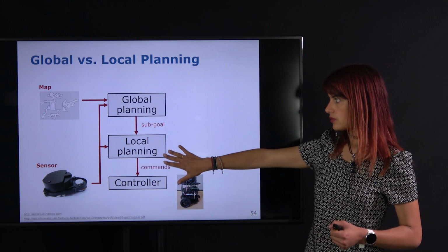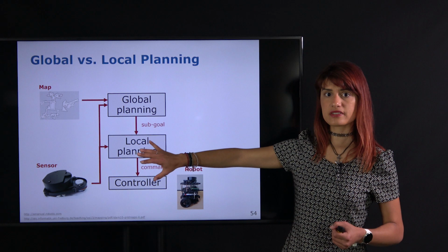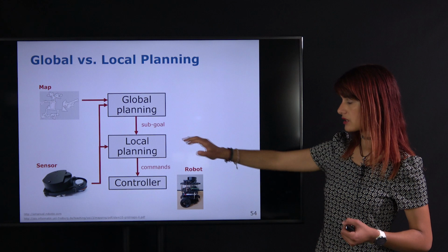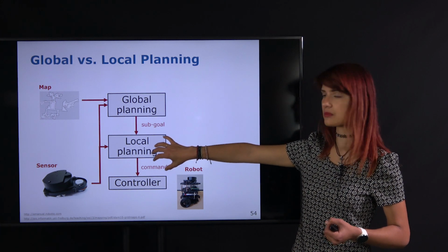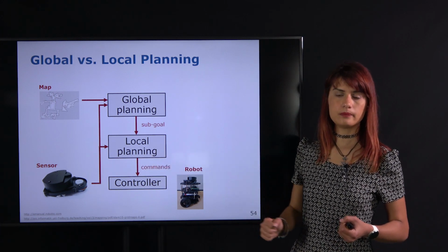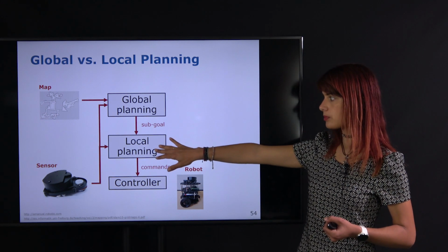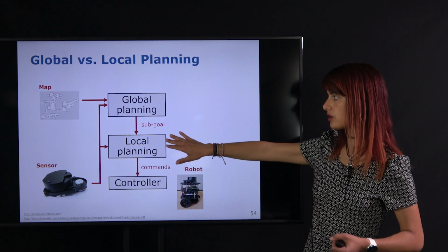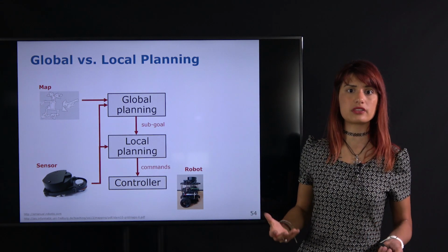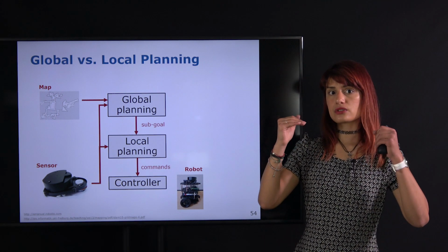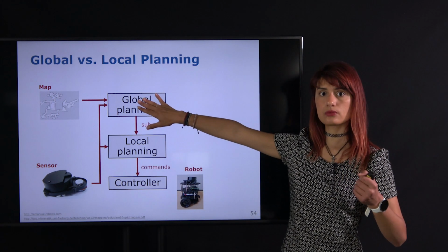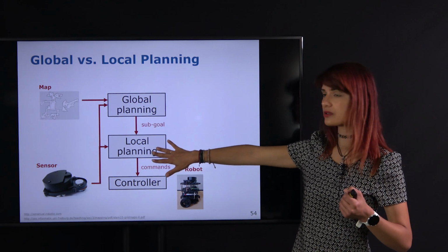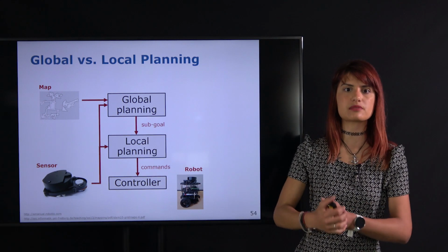Beyond that, we also have a local planner that runs at a much higher frequency, for example, the frequency of the sensor, and actually performs reactive actions and modifications if they're necessary. This is helpful, for example, in dynamic environments. If obstacles are coming up, then the local planner would be able to react and avoid these obstacles. This adds an extra safety layer. Otherwise, as we said, we would simply be executing the global plan without catering for any uncertainties or dynamic aspects of the environment.